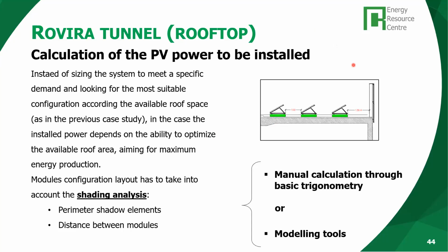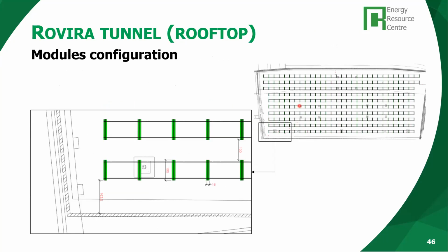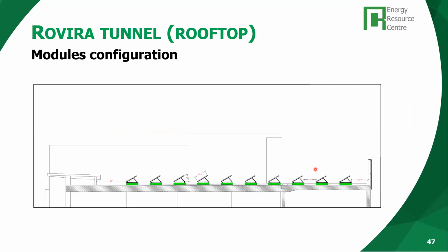And in this case, this meter that you can see in this picture, this meter of separation, it's a short separation, and we were helped by PVSol, the software that is better for me than PVSyst, for doing a very good calculation of the shading, for reducing this distance between the lines, to get much more power in the same space. It's important to think about it.